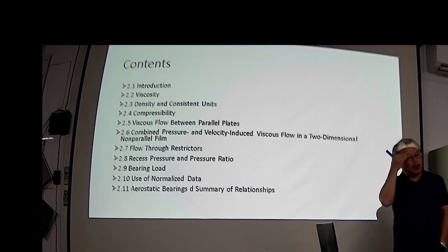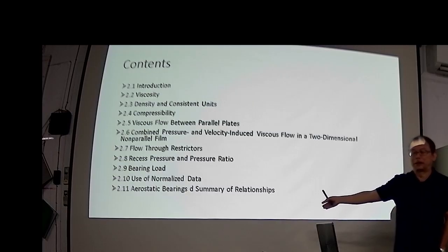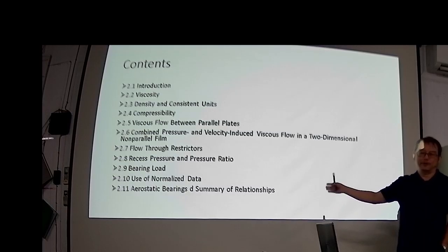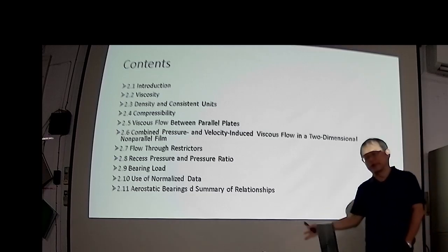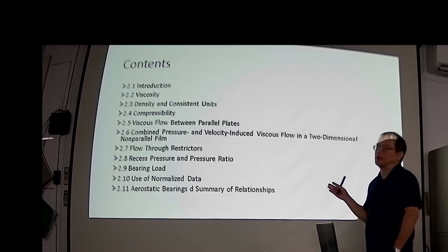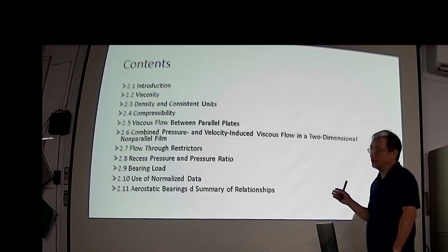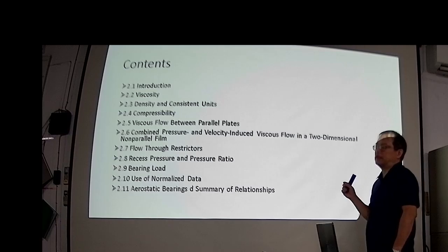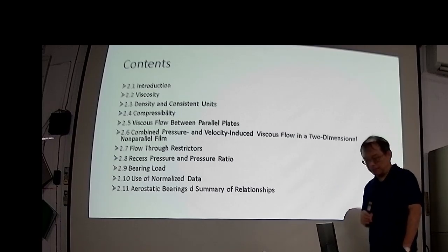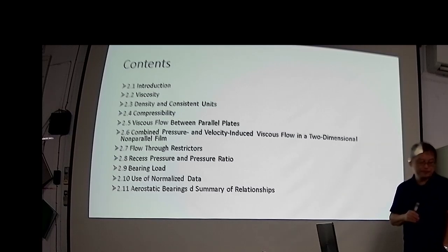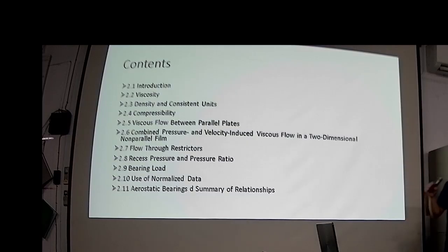You need to know how to calculate the bearing area, the recess pressure, and the flow rate of the bearing, and also the temperature rise from the viscous friction, the pumping power for your system, and the total heat generated between the bearing surfaces.